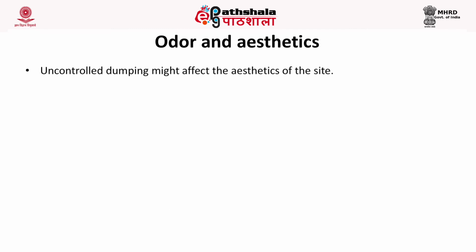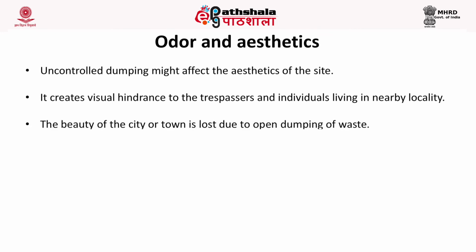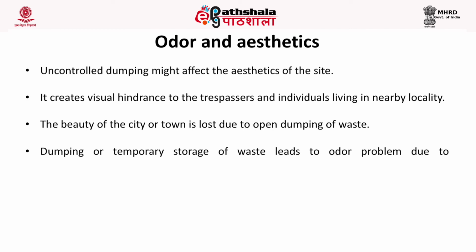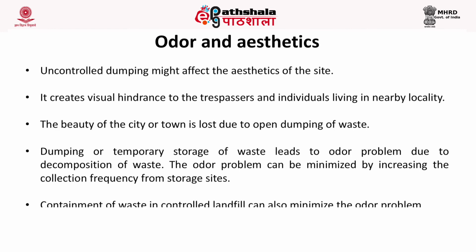Now, uncontrolled dumping might also affect the aesthetics of the site. It creates a visual hindrance to the trespassers and the individuals living in a nearby locality. The beauty of the town is being lost when you see an open dump. Dumping or temporary storage of waste might lead to odor problems due to decomposition of waste. The odor problem can be minimized by increasing the collection frequency from storage sites. The containment of waste in a controlled landfill can also minimize the odor problem.